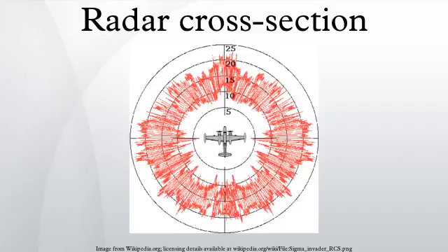Smooth surfaces. The relief of a surface could contain indentations that act as corner reflectors, which would increase RCS from many orientations. This could arise from open bomb bays, engine intakes, ordnance pylons, joints between constructed sections, etc. Also, it can be impractical to coat these surfaces with radar-absorbent materials.